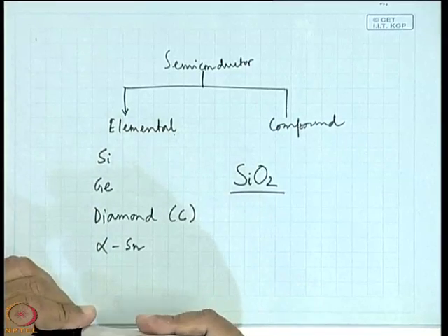Now, for silicon this is an advantage. Why? Because SiO2 can be made very easily. This is basically known as oxidation. When you come to learn about the different steps of IC fabrication in your semiconductor technology class, you will find that oxidation is an important step for fabrication of integrated circuits, like ion implantation, diffusion, annealing, lithography. So, oxidation is a very important process.